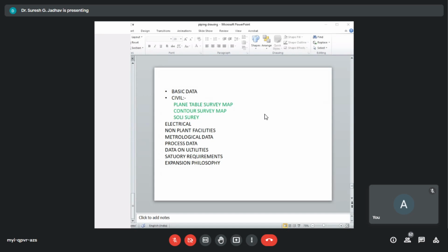requirement of distance to be maintained between the units, requirements for petroleum storage and gas storage, firefighting requirements, height of chimney. These requirements are laid down as per the norms set by the State Industrial Development Corporation, we call SIDC. This is the first statutory body, and second is the Central or State Environmental Pollution Control Boards, we call PCBs. Next is the factory inspectorate. Next is the state electricity boards.